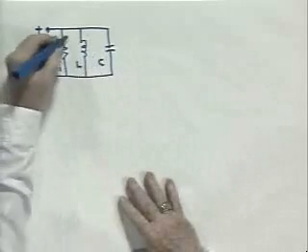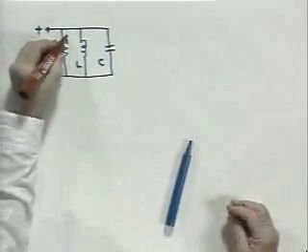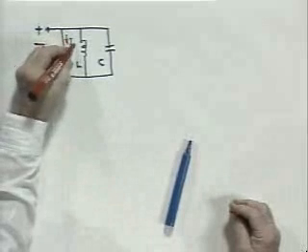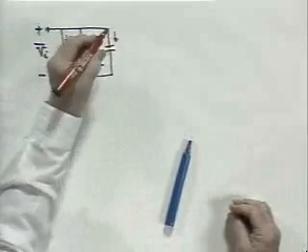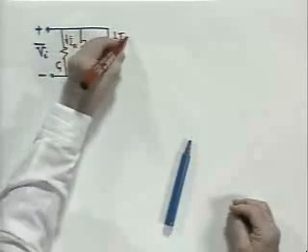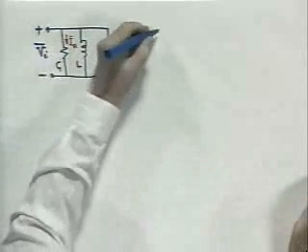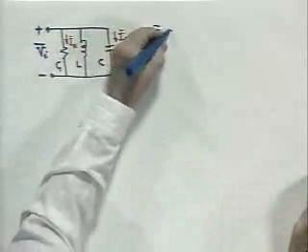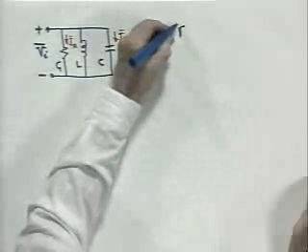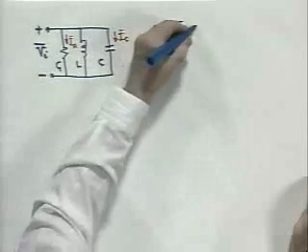The current in the resistor, which I'll call I sub R bar, I want to compare with the current in the capacitor, I sub C bar. The current in the resistor, I sub R bar, is just the voltage across this parallel combination, V sub I bar, times G.